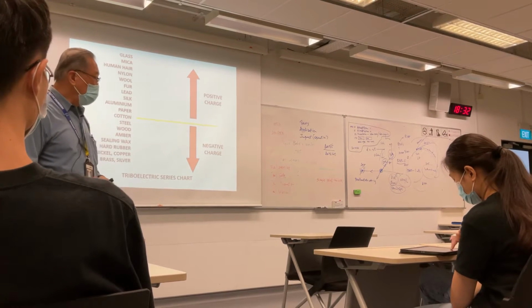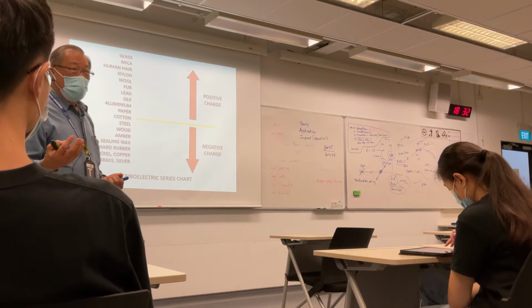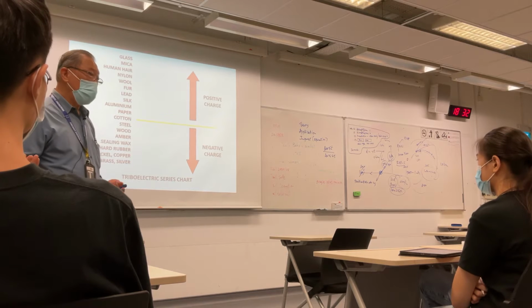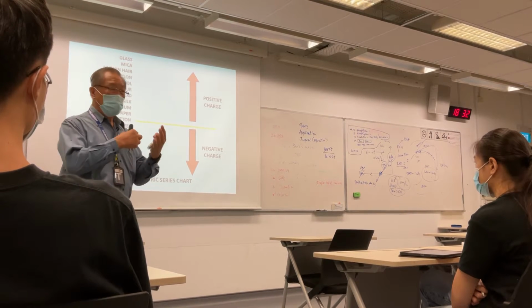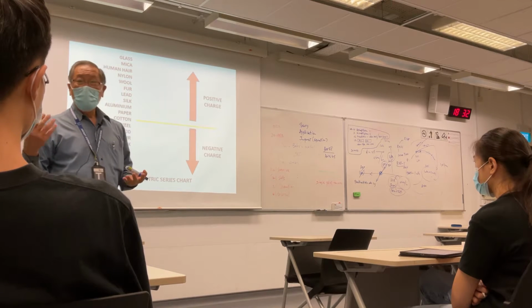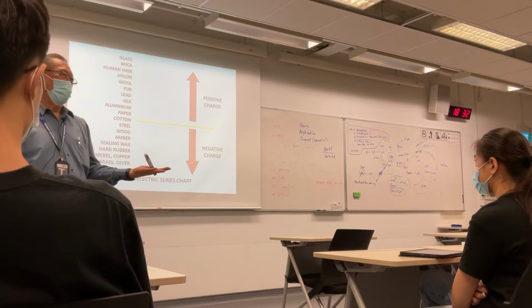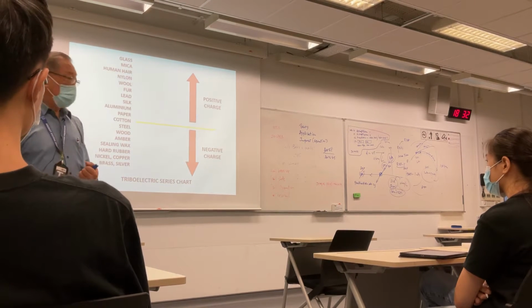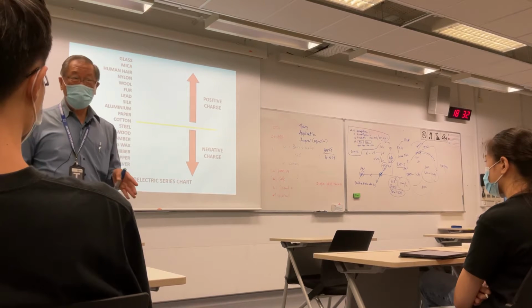Okay. Say for example, you are going to a fuel tank to work. What kind of clothing do you need to wear? Cotton. Cotton, okay? You're not allowed to use nylon because nylon rubbing on the surface of the aircraft can generate static. And then you go to a fuel tank, a static blast, boom, the whole fuel tank will blow, you see? So all of us got to change our clothing too. So you have to understand this for prevent generation. Okay?